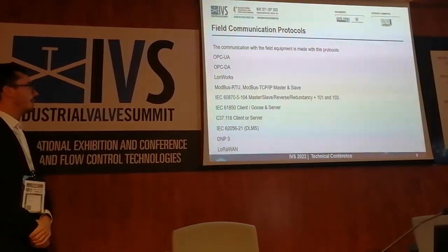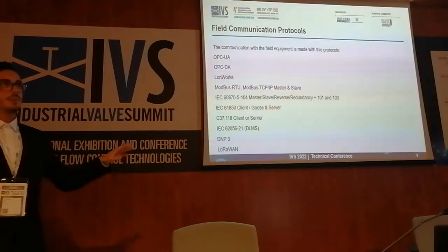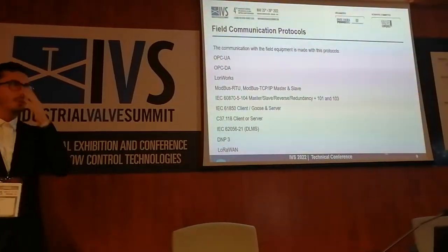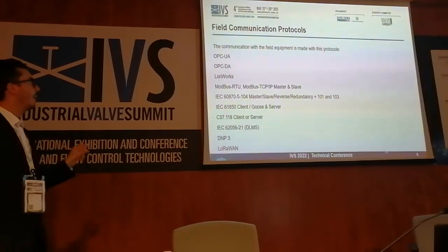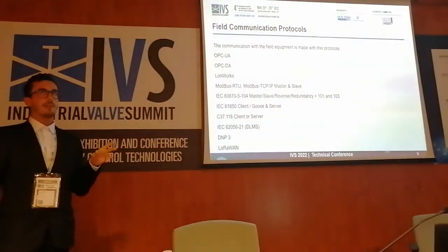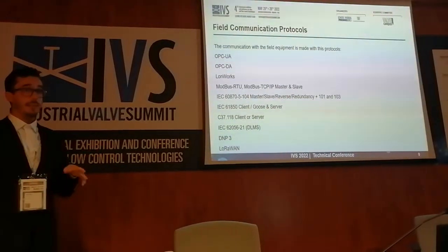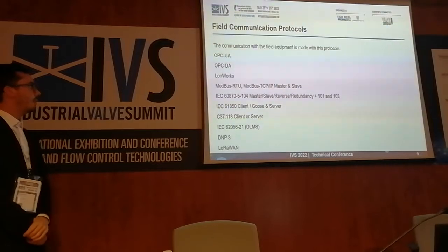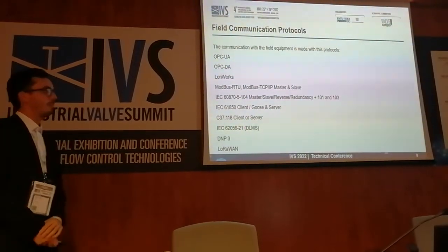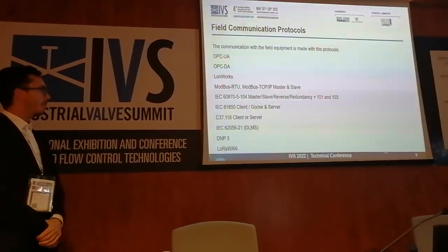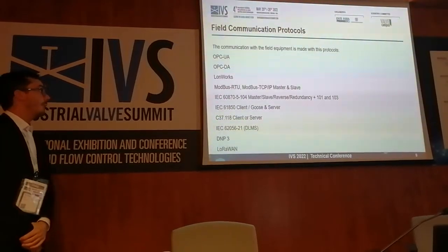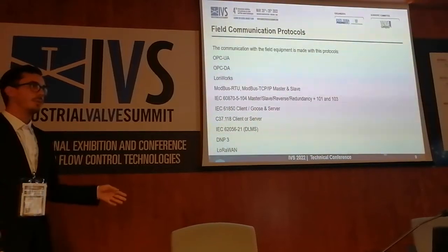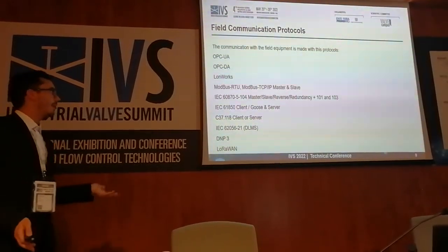Okay, regarding the communication with the field, so we're not talking anymore about the SCADA side, but the field side. The protocols that were involved in this particular project were OPC UA, and some of them were OPC DA. Then the other ones that we are able to support are LonWorks, Modbus, basically TCP and RTU. 1.4 we explained before for the SCADA side, but also for the field side, it's possible to use it as a master or as a slave.